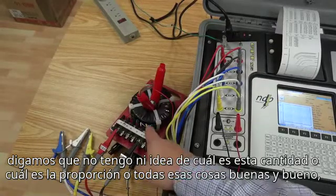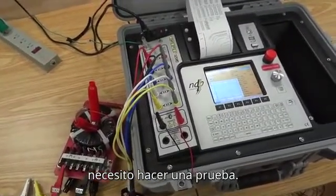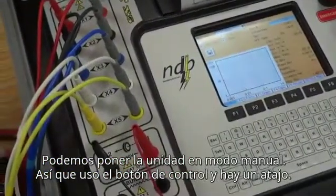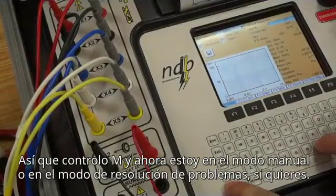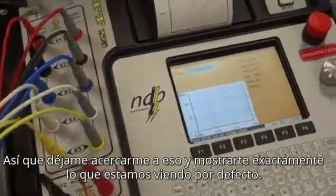Let's say I have no idea what this CT is, or what the ratio is, or all that good stuff, and I need to perform a test. So here's what we can do. We can set the unit in a manual mode. I use the control button and M. This is a shortcut. So Control M, and now I'm in a manual mode, or troubleshooting mode, if you'd like.